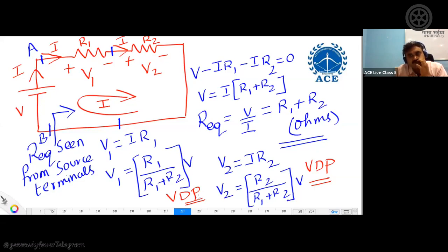Current will be in series, so elements are in series, current will be same, voltage only will get divided. So this is how voltage division takes place on these branches. Okay, derivations, there is no requirement. Actually I am deriving it just to have clarity for you. Most of you might be knowing this, so give importance to this voltage division principle here. That is my requirement.